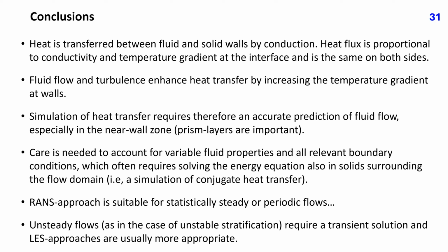The RANS approach is suitable for statistically steady or periodic flows. Unsteady flows, as in the case of unstable stratification, require a transient solution. LES approaches are usually more appropriate.